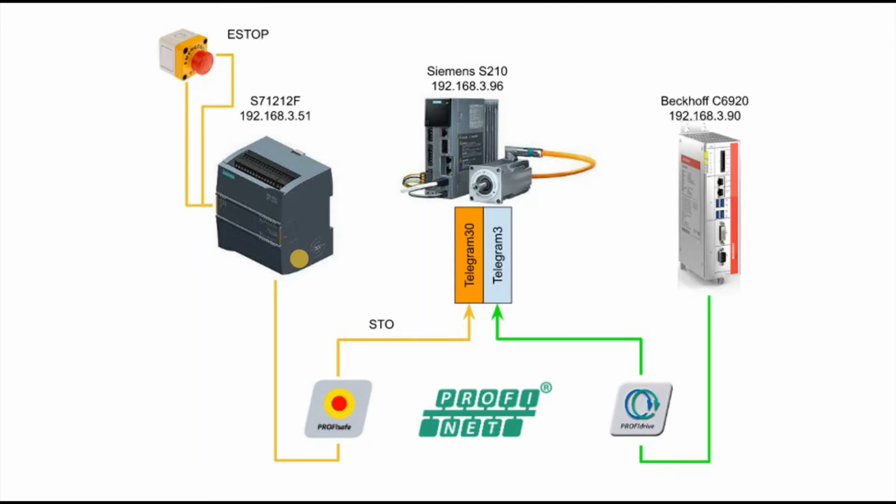Or the next option that you can do is like this. Don't touch anything inside the existing program, add a telegram with the safety application inside, and then use another controller to access this safety part. This can also reduce your costs, because you know a safety PLC is not very cheap, and you need to pay so much. And yes, I've explained the configuration here, so let's go to the next part.